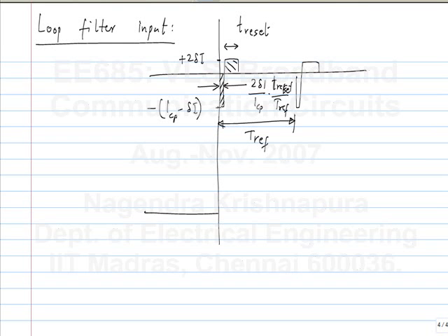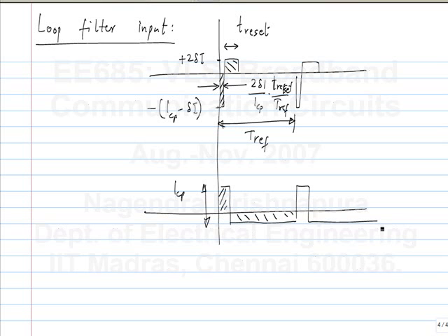Typically, if you have a certain phase difference in a type 1 PLL, the error signal will have a shape like this. Okay. So, error signal is the zero average signal that goes into the loop filter, and the peak to peak amplitude of this is ICP, and then it persists for the entire period. And if the phase shift is more, then it becomes even larger. Okay.